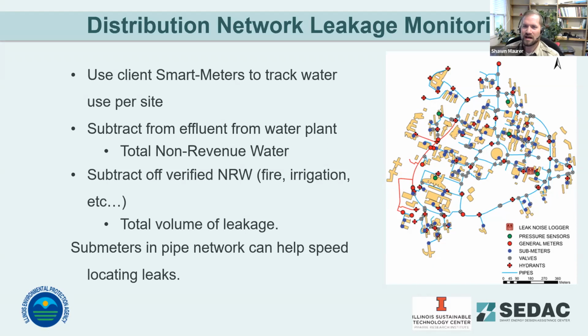You know, if you've got a low spot, then your water plant's up on a hill. That low spot's going to have really high pressure. So usually we see PRVs in place or some other pressure management system. But that's not the only time these are effective.